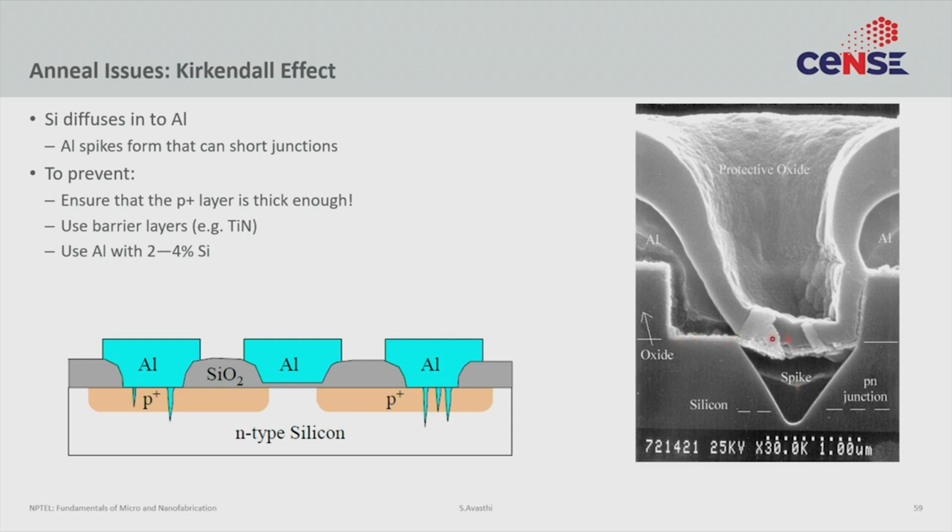So, this is silicon substrate, this is some oxide, you cut a hole in the oxide and you deposited some aluminum. So, this is aluminum. So, that aluminum is touching the silicon and you formed an interface, but then for some reason you took this to say 600 degrees C. If you do that, silicon at this interface would start diffusing into the aluminum.